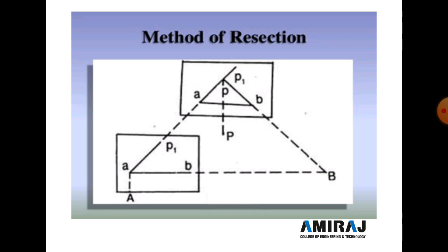Now the plane table is set up at A and perfectly leveled. Then centering and orientation are done on station A, and bisect the ranging rod fixed at point B. The plane table is perfectly clamped, and the line AB is already drawn.